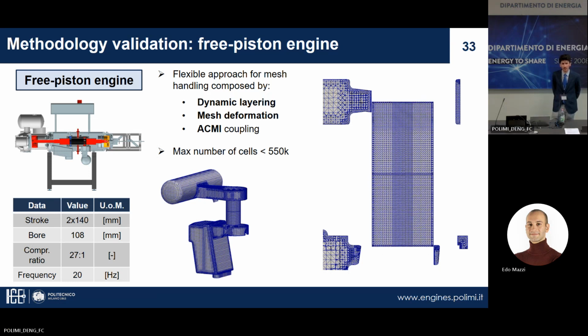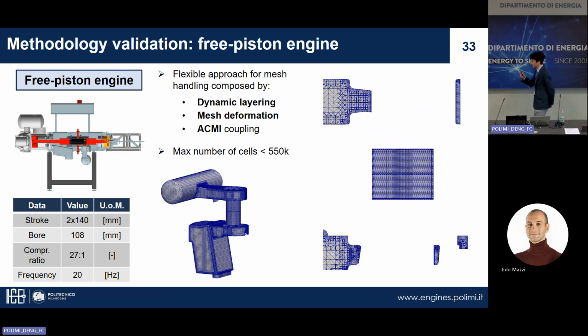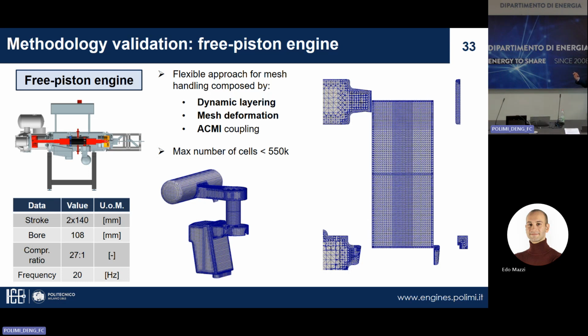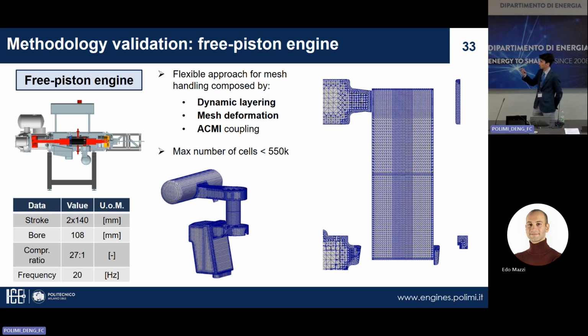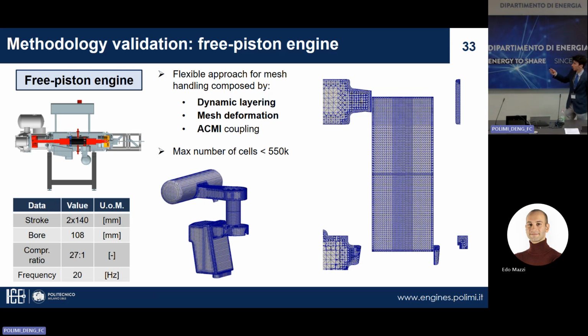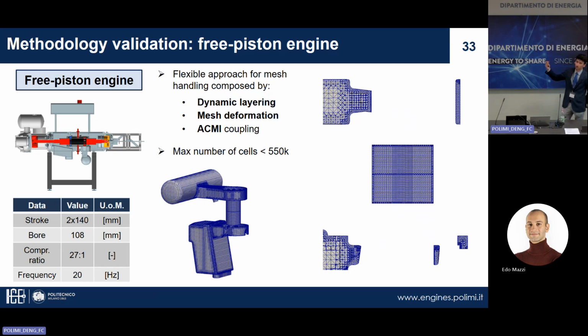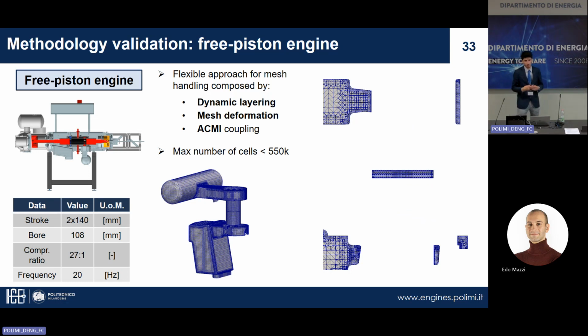You mean, are you able to assign a velocity boundary condition to the moving wall? Yeah, the valves and the piston are all moved according to the motion provided by the engine. So when you provide the engine information like connecting rod length, bore and stroke, automatically we get the engine motion, and we apply this information to the boundary to be moved accordingly to this motion.